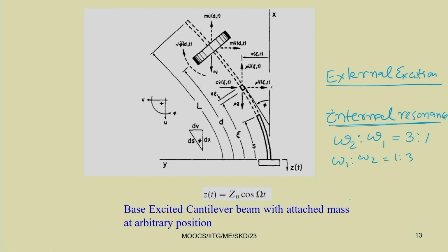Generally it is possible in a system containing cubic nonlinearity. For example, if you take a multimode system, for example omega 3, let us take these 3 modes, then you can have 1:3:5, 1:3:9. These types of internal resonance conditions you can also have. These are known as 3 mode interaction, while this is 2 mode interaction.